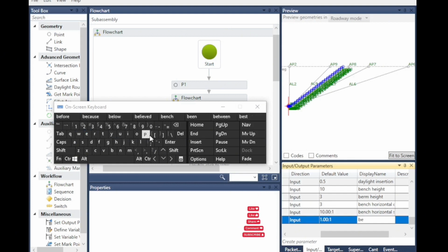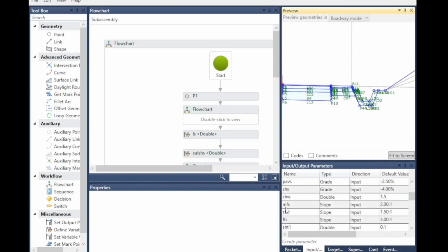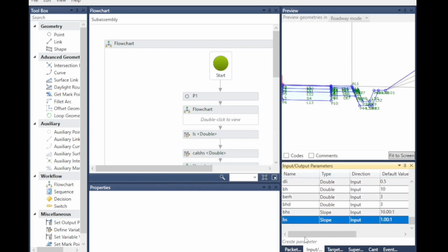Next, we will see undercut or replacement, as we have known. If the existing ground soil is black cotton or expansive, usually the engineer orders the contractor to undercut the existing ground and replace it with suitable material.